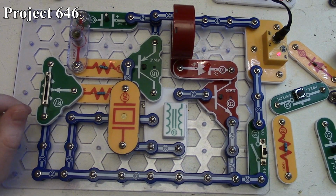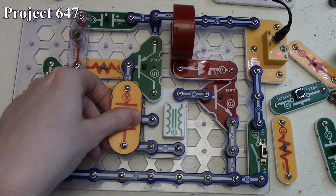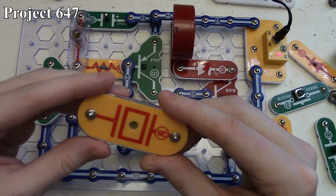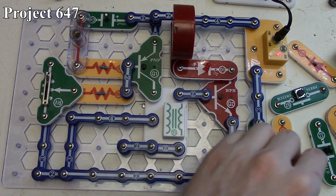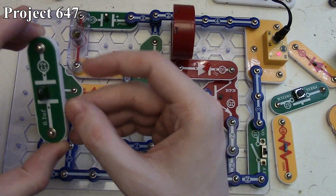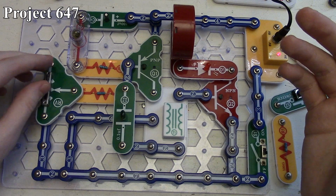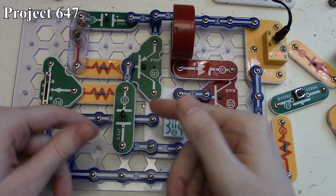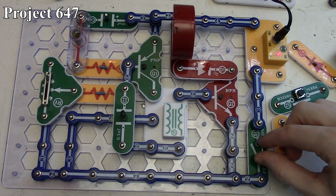So that's how Project 646 works. Now Project 647, we're going to change out the whistle chip here, because this will change the rate of oscillation in the circuit, or the frequency, because the whistle chip itself acts as a capacitor in this case. So we're going to put the C2 0.1 microfarad capacitor there. And since we're increasing capacitance, like we have seen in previous projects involving oscillation circuits, when you increase the capacitance, you tend to decrease the frequency of the oscillator circuit.